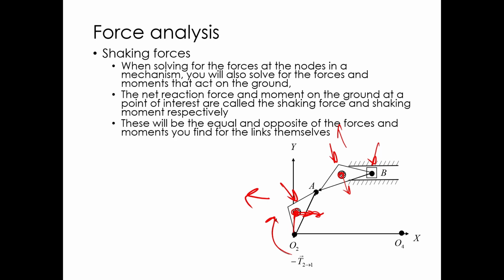So essentially all the masses that are being slung around inside the engine, the equal and opposite reaction is going to happen on the engine block itself. And so that's what we're talking about with shaking forces. It's the equal and opposite of the forces acting on the mechanism to drive the mechanism.